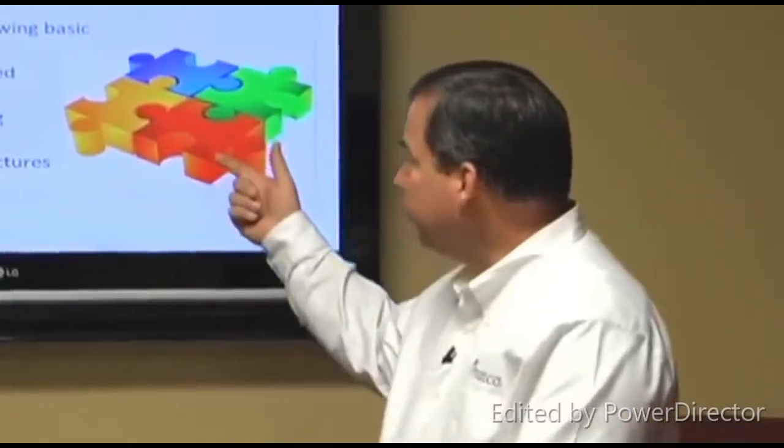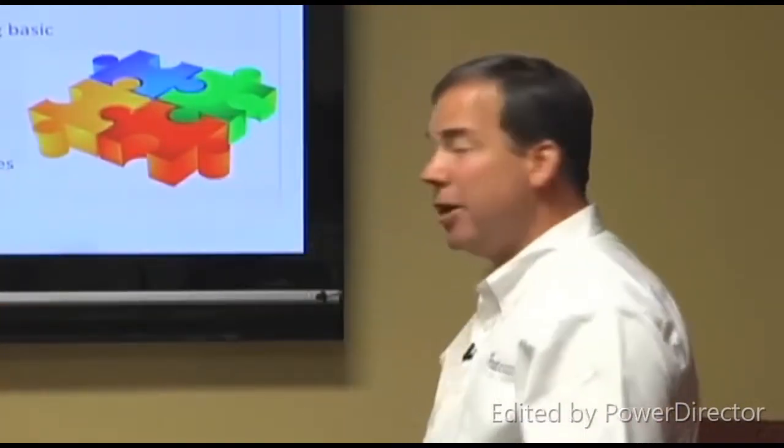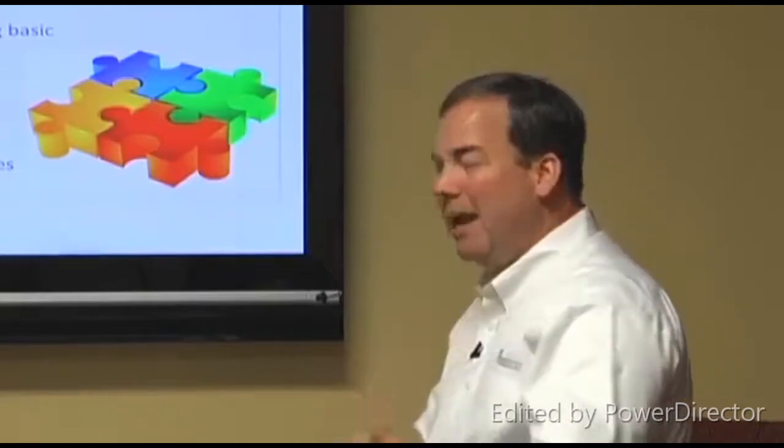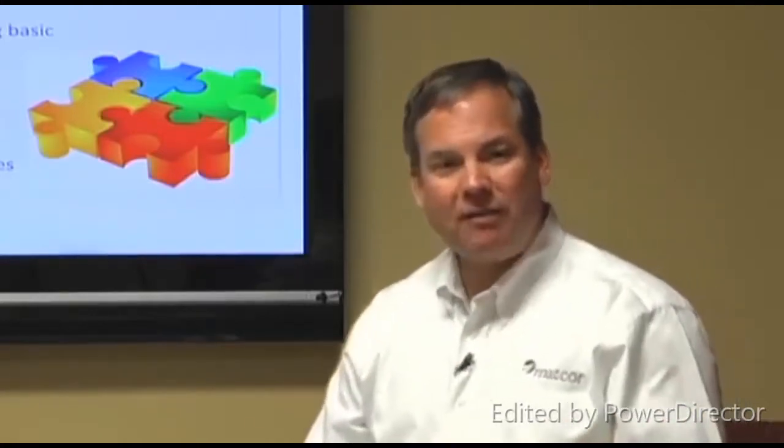So you need a structure to protect. You need an electrolyte that current can flow through. Obviously, you need some sort of an anode to deliver current. These are my lights that are going to light up the structure. And then there's some cabling in there to connect it, because you have to have that metallic path, or that circuit. So you have to have something connecting the anode to the structure. Often there's multiple connections of the anode to the structure.